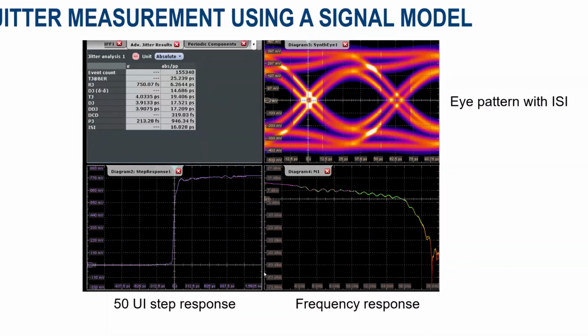So we're 50 bits of acquisition from left to right, and you can see the rising edge. And then there's actually a wiggle here at around 937 picoseconds. That is, believe it or not, the SMA launch off of the evaluation board that I'm using. So you're seeing the signal coming out of the chip, and then there's the characteristic impedance ripple caused by the connector.